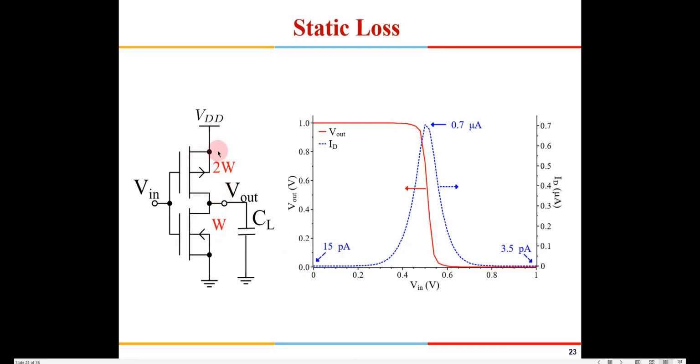So here we are using PMOS to take the output to 1, because whenever the input is 0, the output requires to go to 1. This is an inverter, right? So I am using a PMOS here, which can transmit a perfect 1, so this output voltage will go to VDD. Whereas when I give 1 here, this PMOS will be switched off, NMOS will be switched on, and NMOS transmits a perfect 0, so whatever charge is accumulated in the capacitor will come to 0.